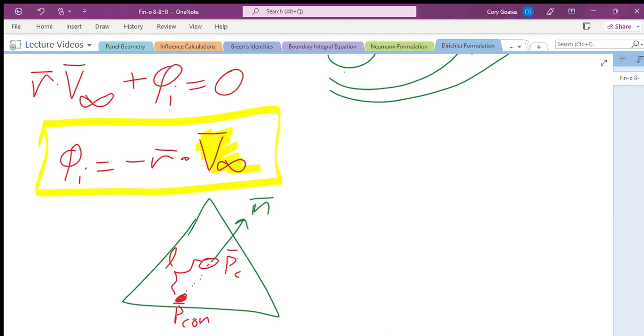See how small you can get it before your results start going bad, see how big it can be before your results start getting bad. You'll find there's a happy medium. At least that's been my experience. It's a really interesting parameter to play with. I find the closer you can get it to the configuration surface, the better, but again, there is some point at which it breaks down.